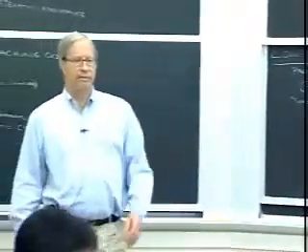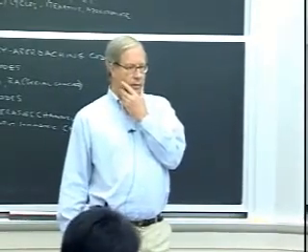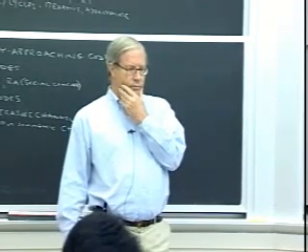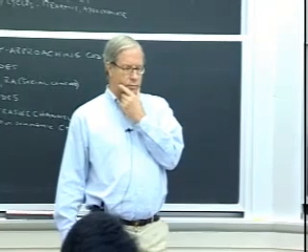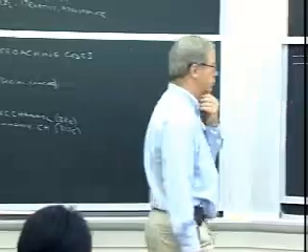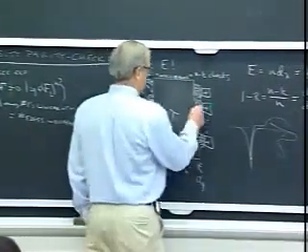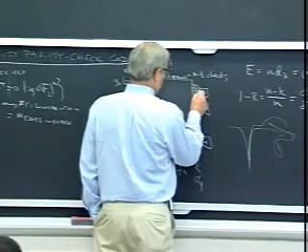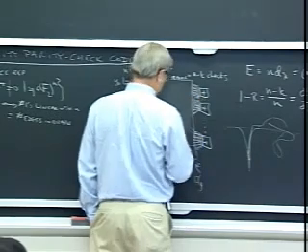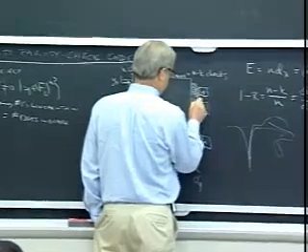Yes? The schedule of the decoding algorithm here. Mm-hmm. So at each zero-sum node, there's one message that arrives, and then you've shown that you calculate one of the messages that go back. So do you calculate all of the messages that go back from each zero-sum node first and then propagate them back to the... Yes, correct. I'm sorry. We not only calculate this one, but at the same time we calculate every other one, all E of them.